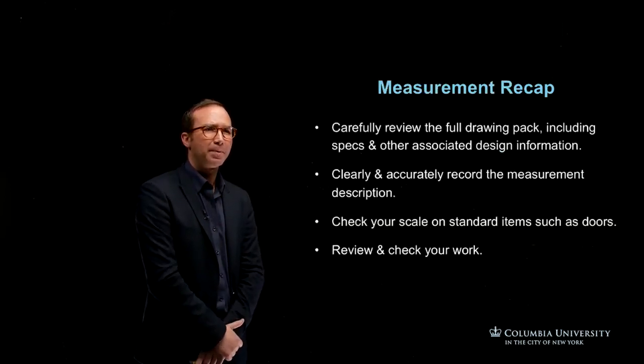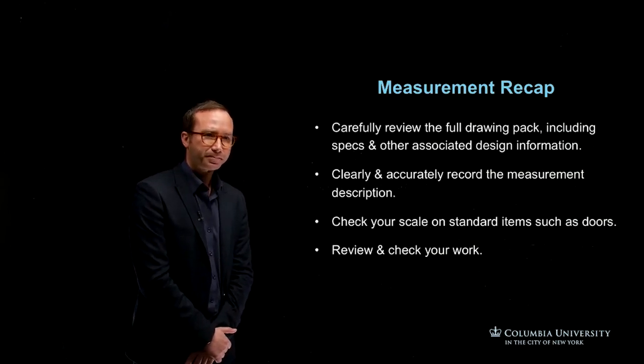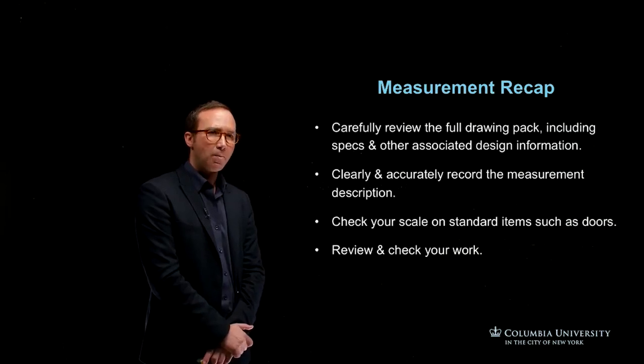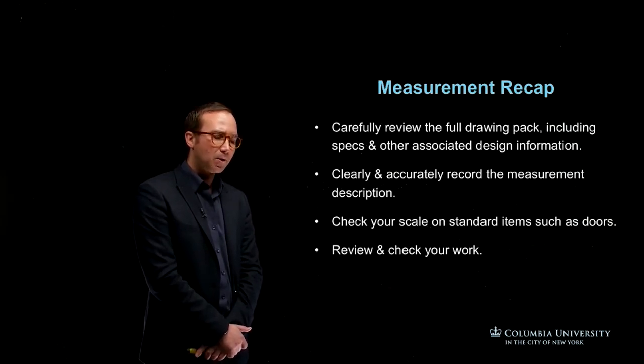So measurement recap. Carefully review the full drawing pack, including specifications and other associated design information. Clearly and accurately record the measurement description. Check your scale on standard items such as doors. Review and check your work. So you must review your own work, that's very key. You need to make sure you're comfortable with it. And then it would be very good if you can get someone else to review your measurement as well and do spot checks.